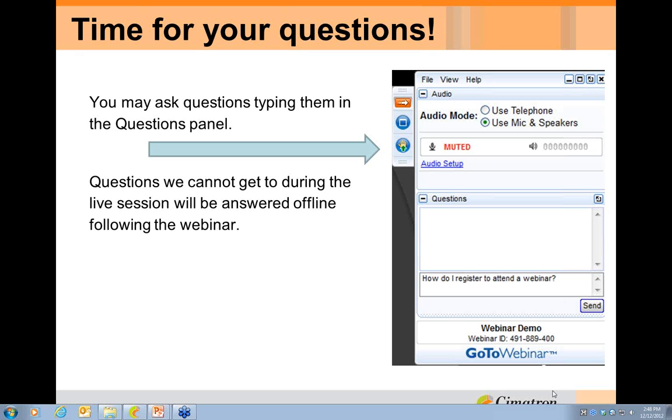And here is what looks like it might be the final question. Do you have to have your parts quick split in order to use ECO Manager? No, you don't. You saw me using it a lot, but because quick split is so involved, so vital to the process of how we pass stuff down into cores and cavities. I mean, that's how we know what goes to what part. Is it assigned to the blue? Is it assigned to the pink? Or many of the other sets. And so in the cases where I wanted to update, I needed to do that, so it knew where to take what surfaces.